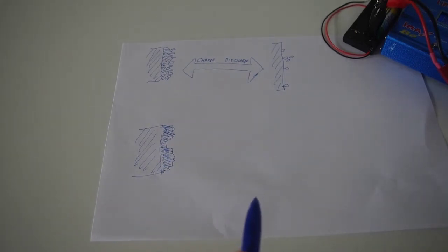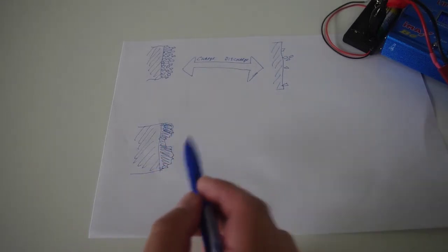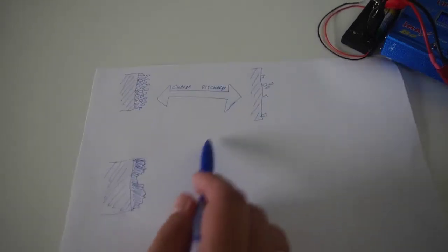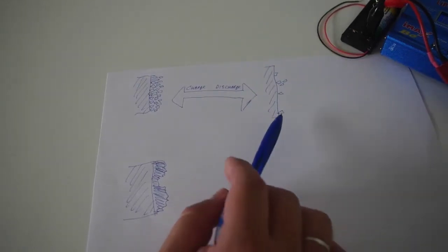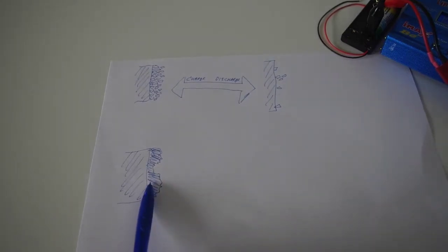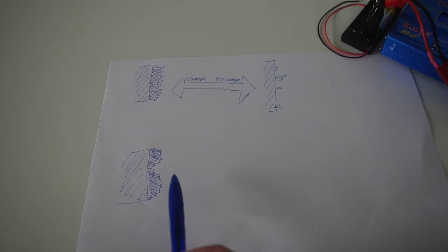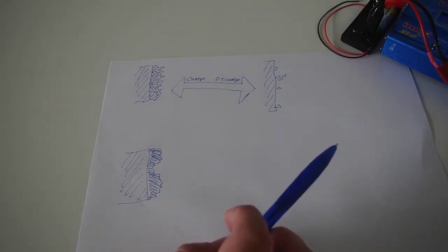Can we somehow fix it? I think yes. I think there is a way to fix it. This structure, this big crystal, will be dissolved into something like that if we fully discharge the battery, but the difference is this will be dissolved really slowly. So what we need to do is fully discharge the batteries with NiMH like I did, or with some other load.